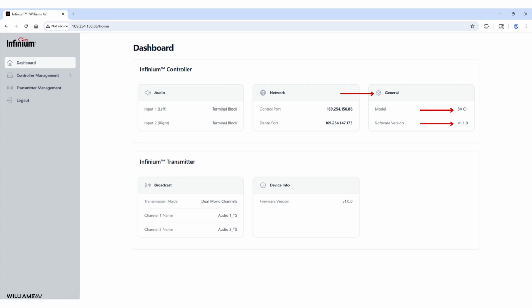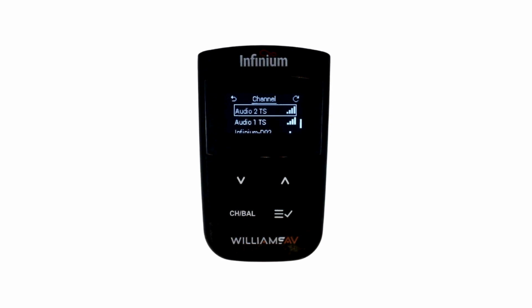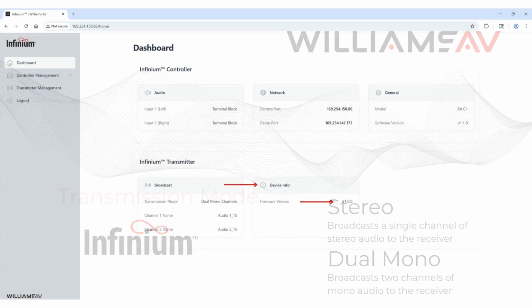In the Transmitter section, under Broadcast, this setting shows whether the audio is being transmitted in stereo or dual mono. In stereo mode, the receiver will see a single channel to choose from, and you will hear true stereo sound with distinct audio in the left and right ears. In dual mono mode, two separate channels appear on the receiver, each delivering mono audio, the same sound, in both ears. This allows flexibility depending upon your application, whether it's music, speech, or multiple sources. Under Device Info, we can see the transmitter's current firmware version.